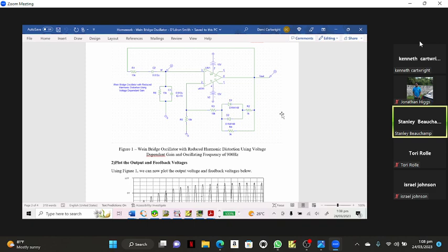3.2? No. Where do you get 3.2 from? I thought R2 would have been connected. When the diodes are on, R2 is connected. So if R2 is connected, what's the gain? Is R2 in parallel with R4? Very good. R2 is in parallel to R4.